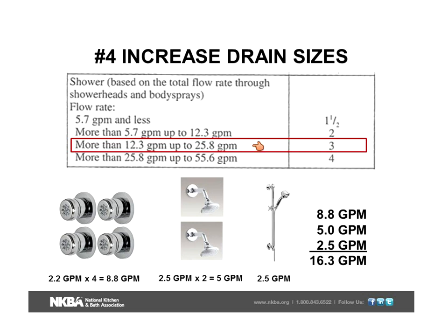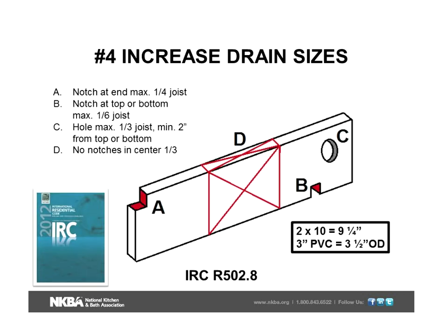That means we have to have a 3-inch drain. So we just jumped from the bathtub drain to what we would need for the typical toilet. Now the problem there is we cannot run perpendicular to floor joists. You better hope you have floor trusses in that home. Of course, buried in a concrete slab, it even gets worse than that.